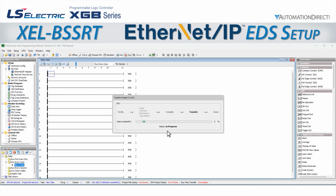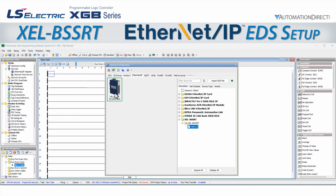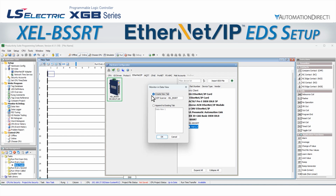Now let's create a data view window for the Ethernet IP information tags we created earlier. The productivity software makes this easy because we can go back into our hardware config, right-click on the BSSRT, and select Monitor in Data View. The software then asks us if we want to create a new data view or use an existing one. We will create a new one.